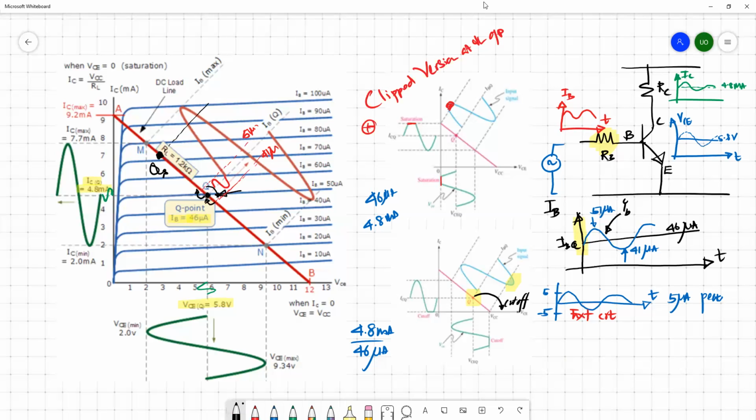With that cutoff, you know that your collector emitter junction voltage is basically pushed to the supply voltage, and you can't see any amplification. So the output is basically saturated here and fixed at VCC, and you can't see any kind of amplification beyond that limit. At the same time, your collector current simply drops to 0 and you can't see a perfect amplification during this period as well.